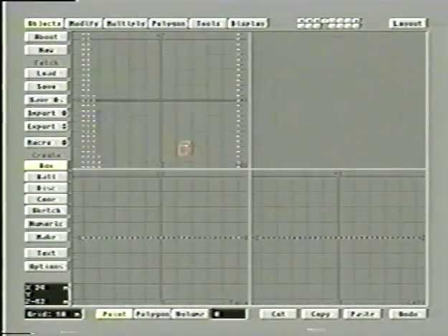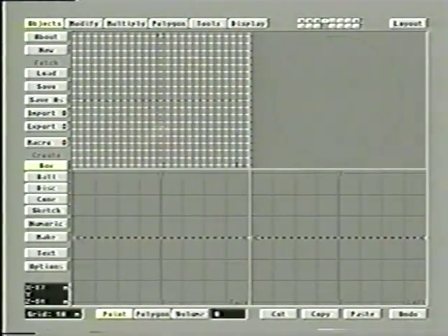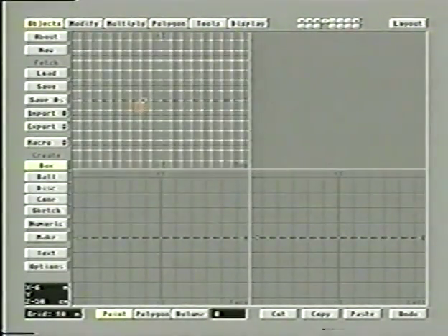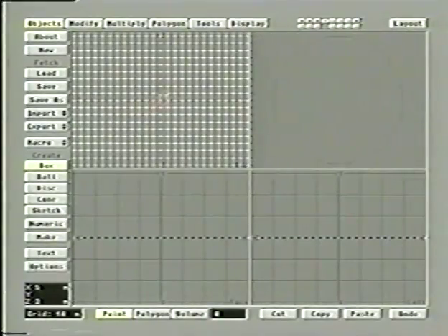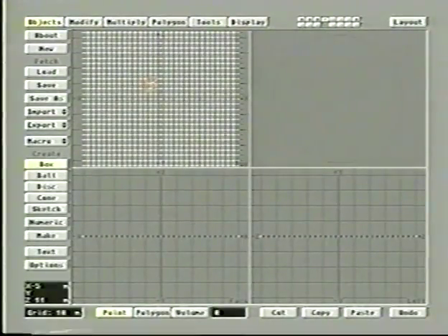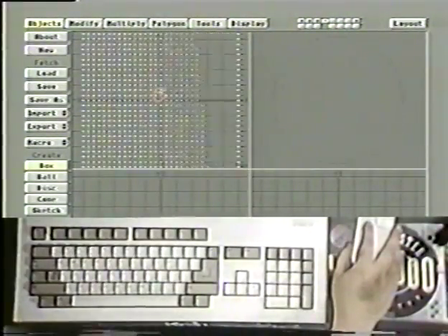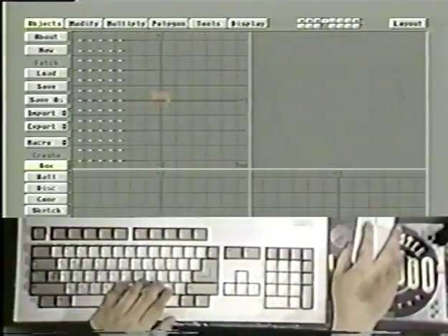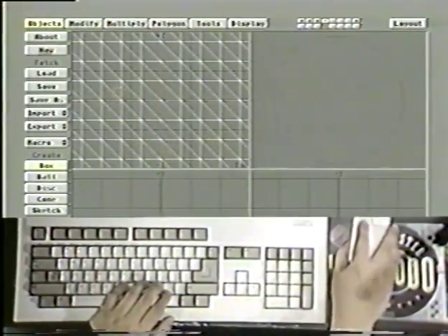If we zoom in here, you'll see it's created a nice mesh of polygons, or as I sometimes say, a mess of polygons. You've got a lot of polygons here in this flat shape. Now what we're going to do is triple it. First off, Shift-T, because I know I'm going to be deforming this and I want it to render properly. And tripling it just turns these polygons into triangles.